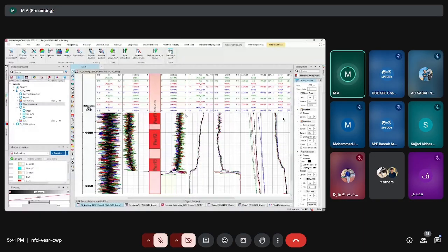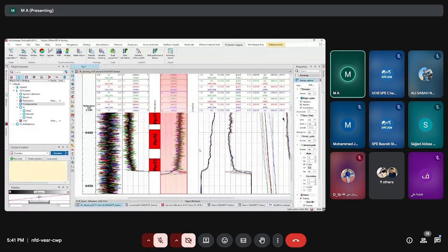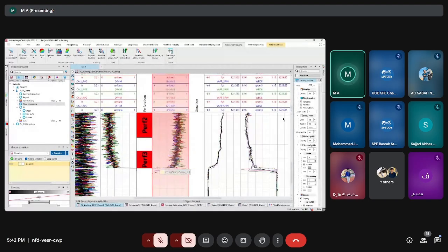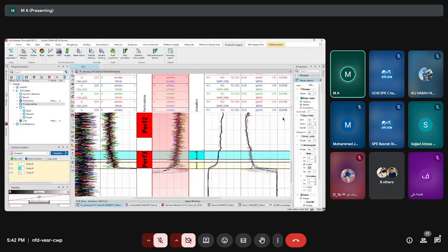So what I'm going to do is insert a new zonation, matching with my perforation. Instead of having one perforation, I'm going to create a zone across whichever area is producing. For example, from here to here, this is 100% sure it's producing. From here it's a kind of straight line, so there might be nothing. So I'm going to check, okay, I also have this here, right? So this will be, for example, my inflow zone across this one.